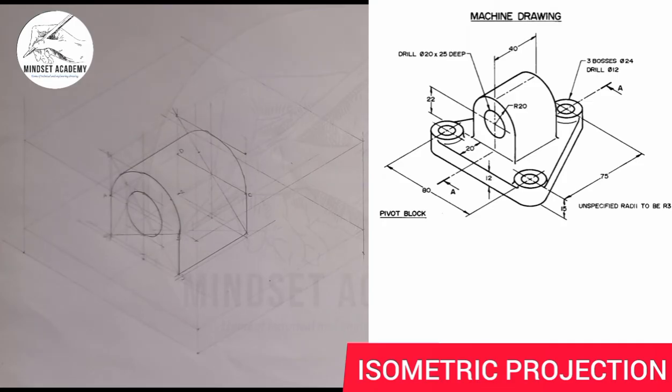Now the next thing we'll have is to draw the two figures we have here, the two circles we have here. So we know from here to here is given to be 15. So again, 12, sorry. So the height of that circle there is 3 millimeter above this line, because 12 minus 15 gives you 3. So I'll just increase the height to 3 millimeter this way.